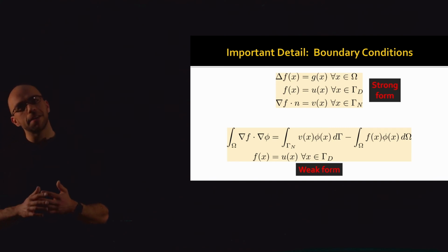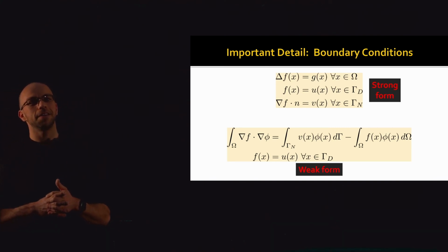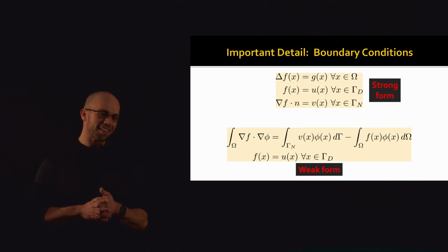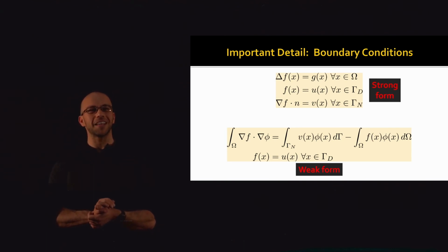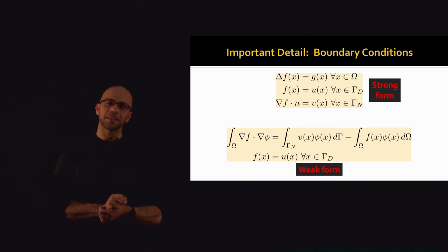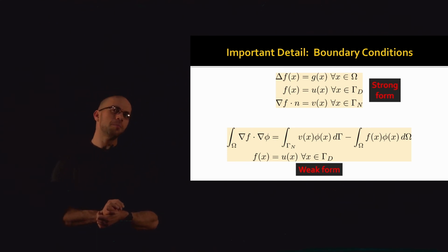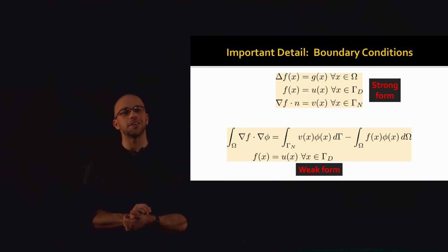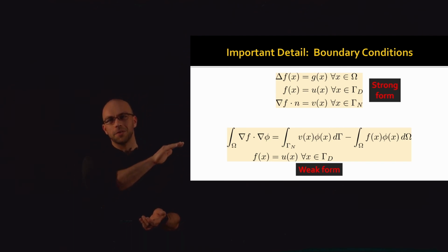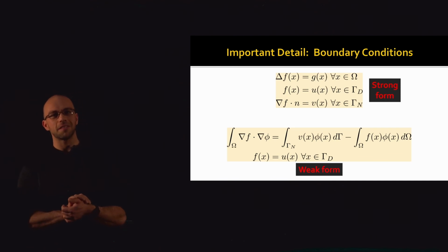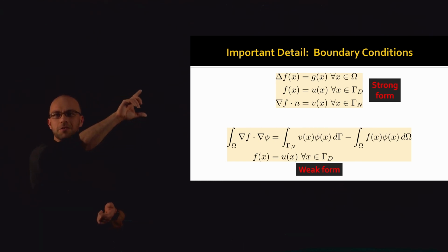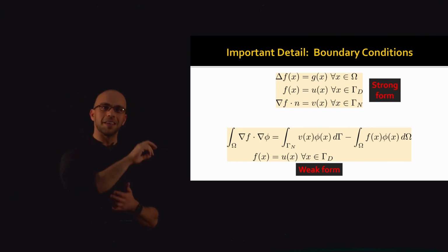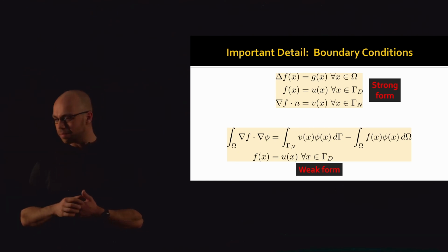Now, an important detail that we've omitted, of course, is boundary conditions. My postdoc, Oded Stein, is an expert in PDE boundary conditions, and maybe we can invite him to give a guest talk in this class. Essentially, nothing too miraculous or special happens in the boundary condition case. We just have to be careful that when we compute our integrals against test functions, we incorporate whatever boundary conditions we need. That's basically the only difference. And so that's something to do with the transition from our strong form PDE to the weak form PDE, which is the one that FEM is working with.